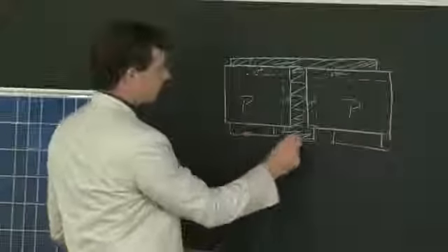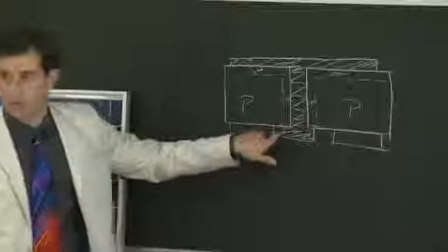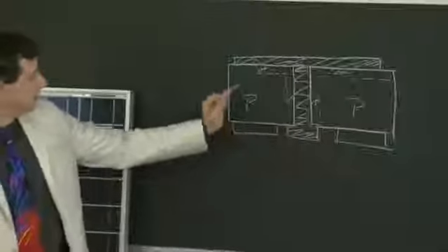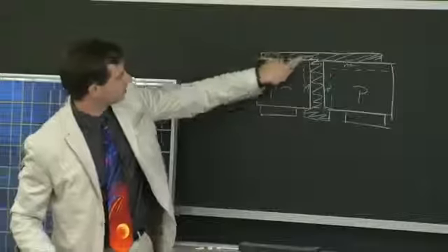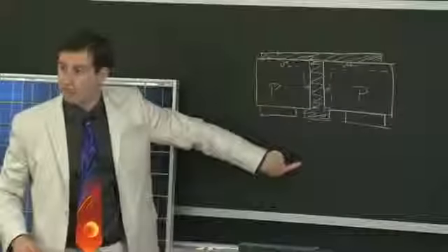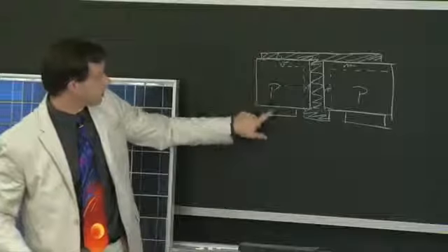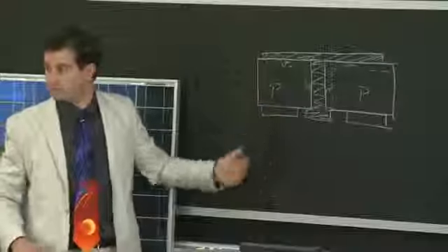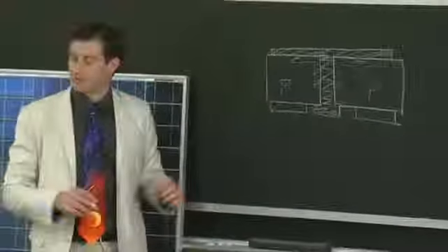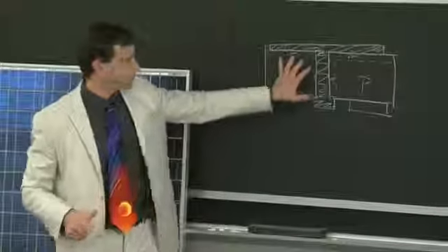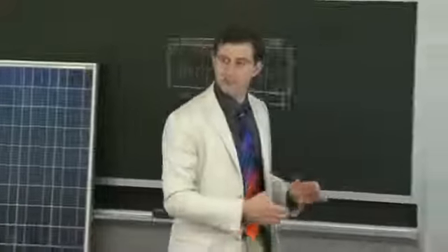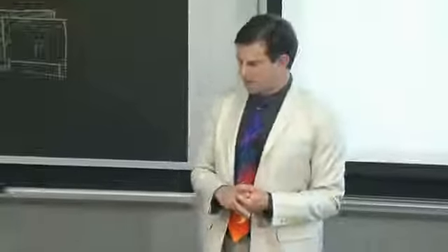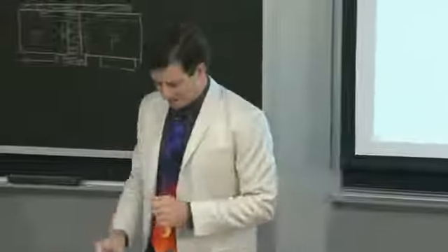And as long as there's no metal short between the electron and hole, say, for example, you generate an electron hole pair here. The electron goes up to here. It goes through the metal to the back and gets pulled out. And the hole goes to this contact over here. And that's how you separate the charges. So this would be an example of an emitter wrap-through or metal wrap-through device technology. Also shown MWT, metal wrap-through.